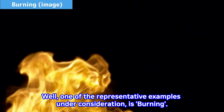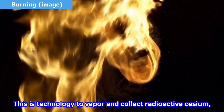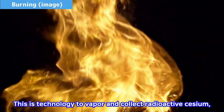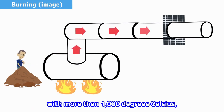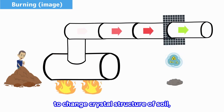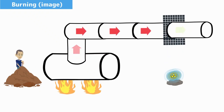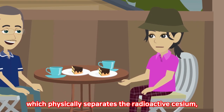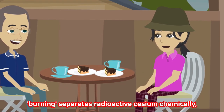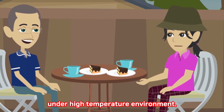Well, one of the representative examples under consideration is burning. This is technology to vaporize and collect radioactive cesium, bound to soil particles, by adding an additive and heating under a high temperature environment, with more than 1000 degrees Celsius, to change the crystal structure of soil arising from decontamination activities. In contrast with the aforementioned classification, which physically separates the radioactive cesium, burning separates radioactive cesium chemically, under a high temperature environment.